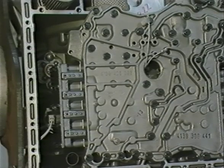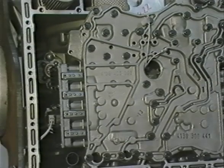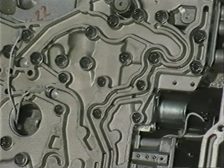When replacing the valve block, ensure that the sensor wire is not trapped, and remember to use a torque wrench to tighten the retaining bolts on the valve block and sump. It is vital when carrying out any work on the gearbox that every precaution is taken to avoid dirt entering any part of the gearbox or hydraulic system. Failure to observe this recommendation may result in gearbox failure or a series of intermittent faults.